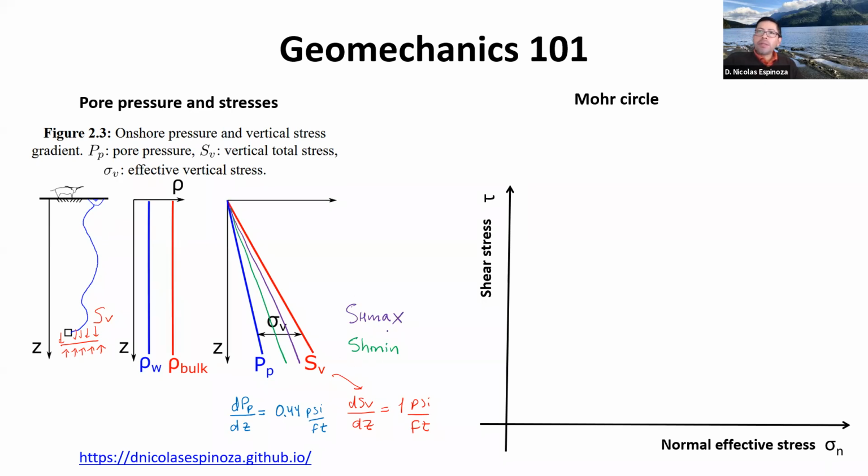What are the values of these? We really don't know. We have to measure those. There are some approximations of those, as we're going to see in just a bit. But if you really want to know those, you have to go to these places and do a hydraulic fracture test and measure those. That's the way of getting these numbers.